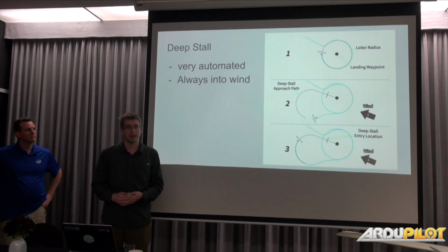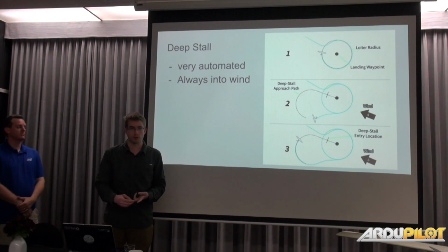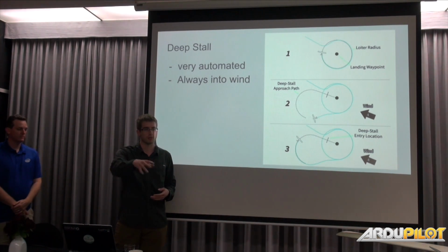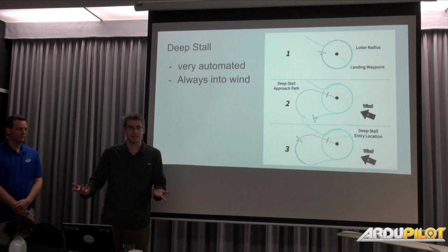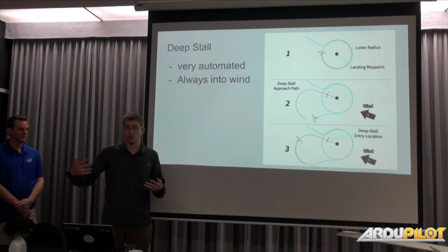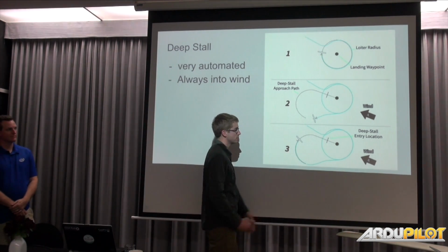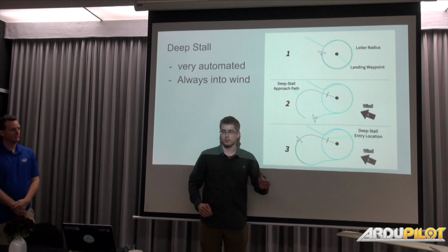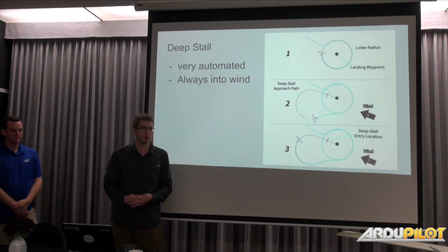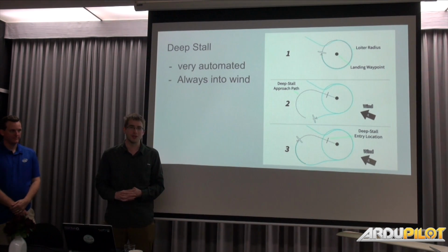And then once you're doing the descent, there are two numbers. One is your forward speed, assuming no wind, and one is your downward speed. So for a parachute, these are what you bring in quite easily based on your parachute. I'll drift this far forward with my speed or not. Your forward speed on a parachute is probably 0, but depending on your shooting style, that's not the case. And then that'll take into account the wind, and also take into account any crosswind component that's developed here. So even if there is a crosswind by the time we get here, because we can't chase the line forever, we'd enter being out of heading. So we'll take into account all of those components. But this is all just a statistics problem at this point. There's not a good tuning approach to this.